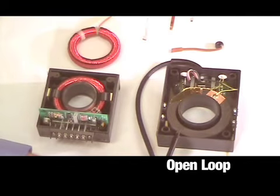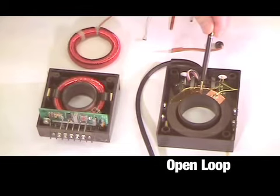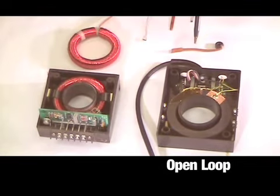On the right, you can see a simpler design. This is the open loop. Again, it's distinguished by the fact that there's no coil around this core. The Hall sensor is down inside the gap of the core, down in this area. And there is a small amount of electronics to signal condition the output. I think this one happens to be a 4 to 20 milliamp output.